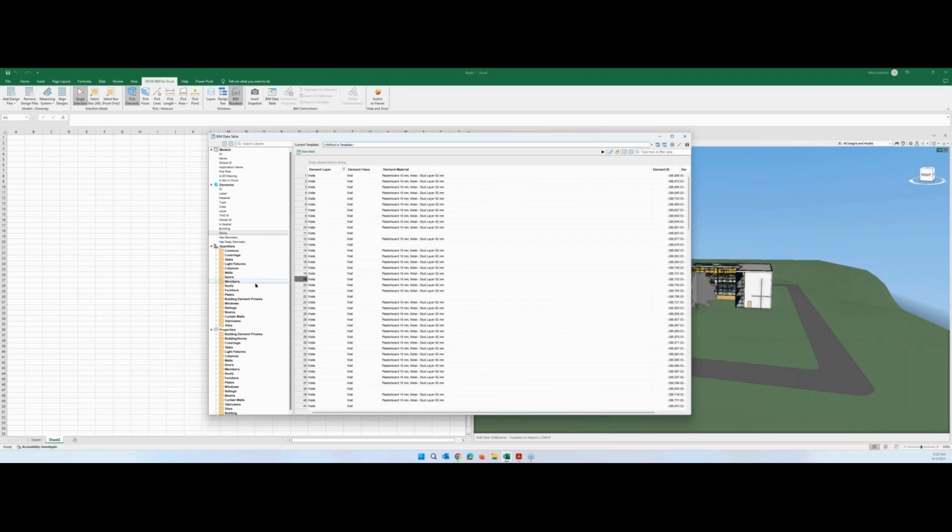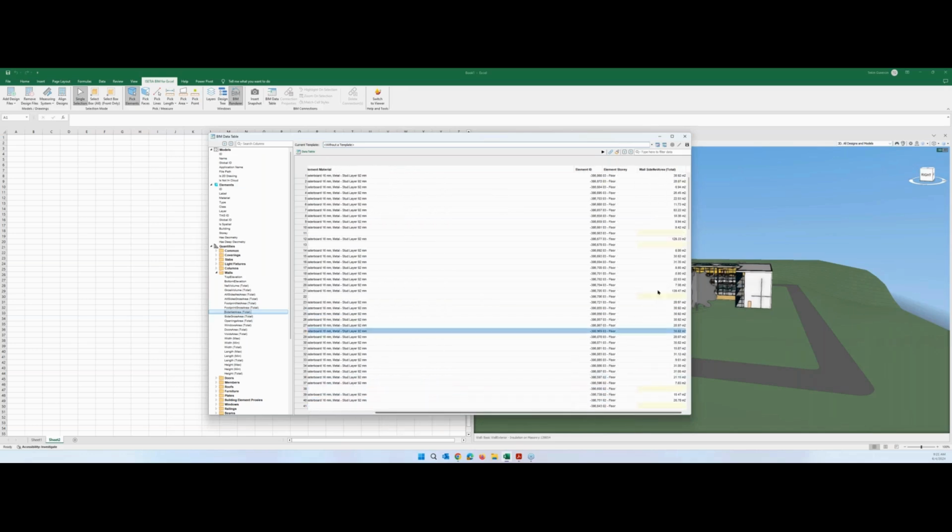And I would like to put quantity. You open the wall, you go to the quantity area. You can, of course, put the size and all the technical things, but I would like to put the total net area. So I can select it here, all site net area, and here total, and I have almost all the quantities, all the information ready.